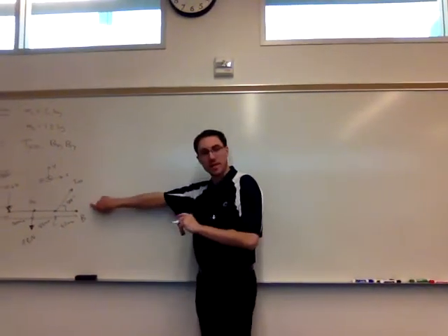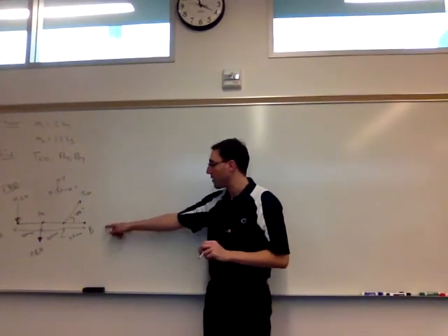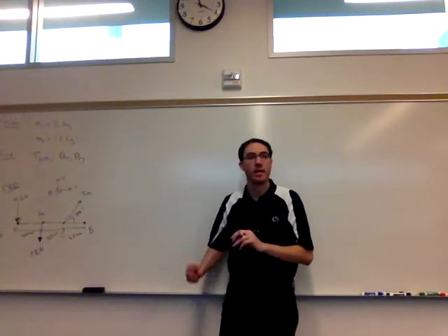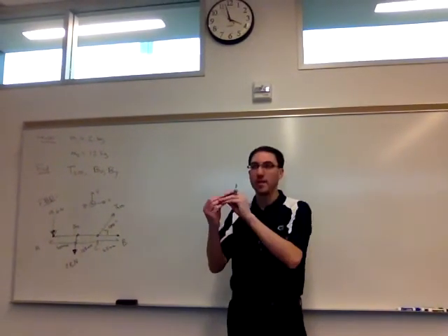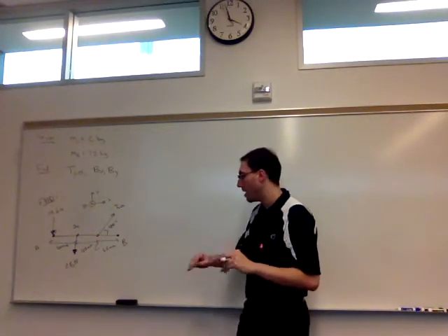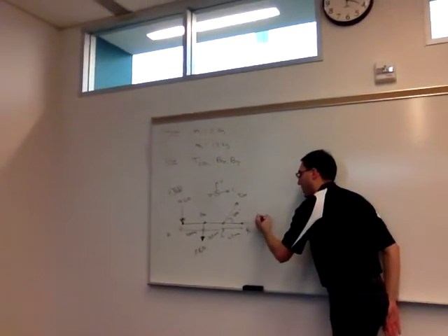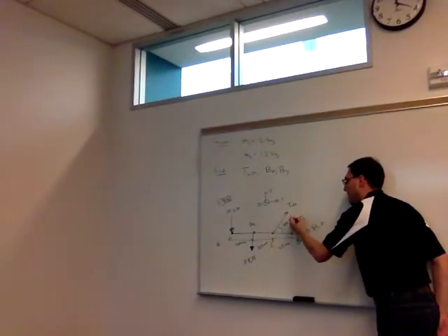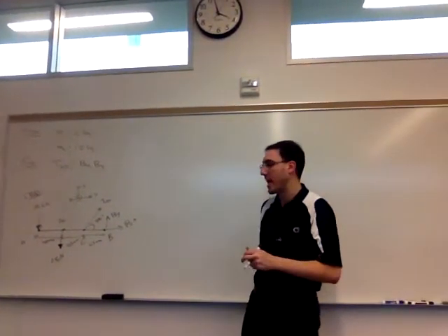Right, so B, we're not done yet. B, we disconnected from the pin. So what do we have to have to model that pin that it used to be connected to? Right, so the pin is restricting force in all directions in the plane. So for the pin, usually the easiest way to do it is we'll model it as its components, and then if we want to know the magnitude, we'll get that out at the end.